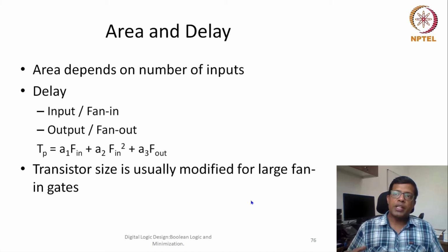They try to make the impact of this fan-in as minimal as possible, but that would also have a side effect in terms of a much larger increase in area. So for now we can say that yes, there is an impact of fan-in and fan-out.